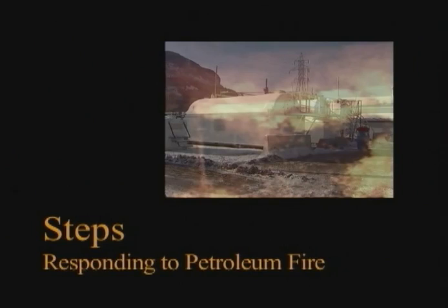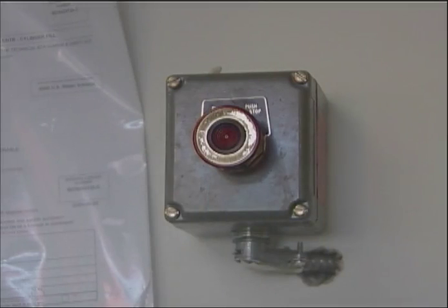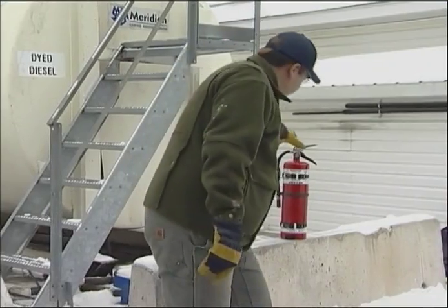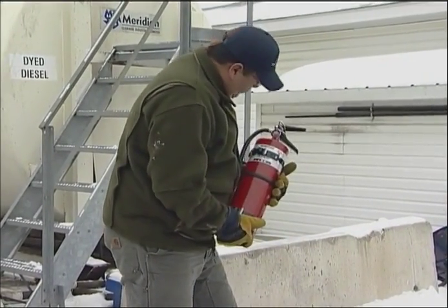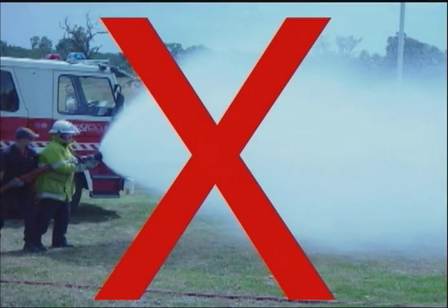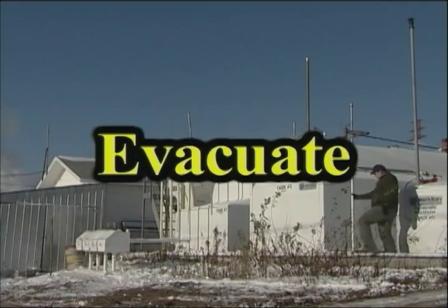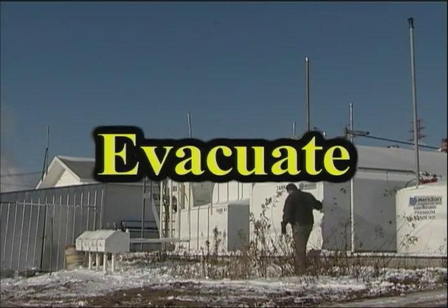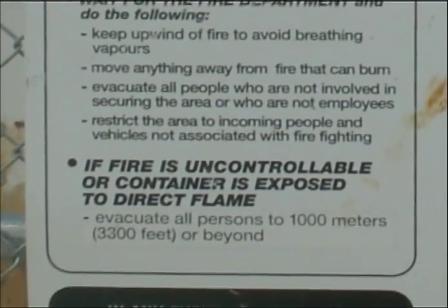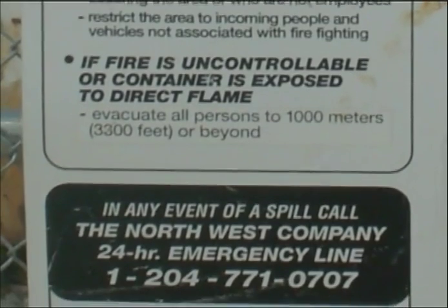The following is a list of steps that should be followed when responding to a petroleum-based fire. Stop product flow. Depress emergency stop button to shut off fuel pump. Isolate the area. Only use fire extinguishers that are approved for petroleum fires. You should never use water to try and extinguish a petroleum fire. Water will only make matters worse by spreading the fuel, making the fire larger. For large fires, evacuate 1,000 meters for gasoline and 300 meters for diesel. Assess the situation, contact your immediate supervisor, and call appropriate authorities.